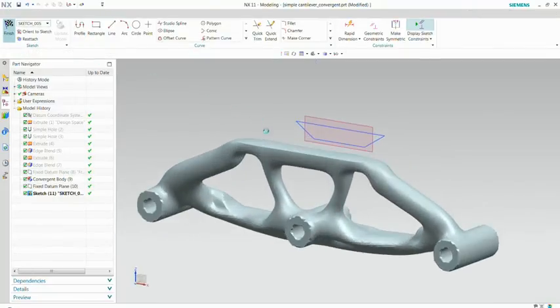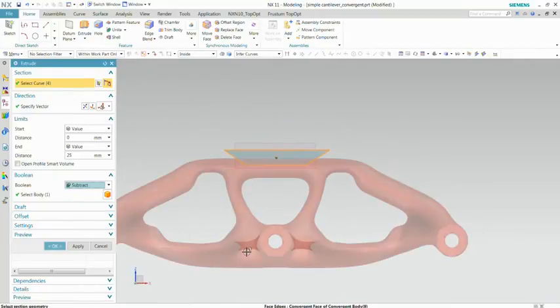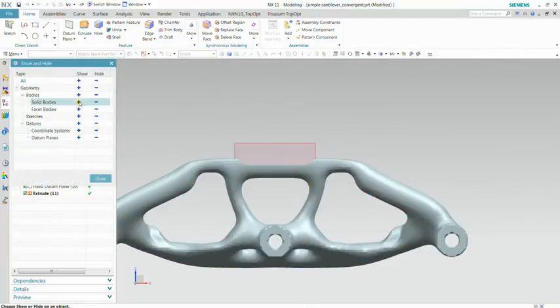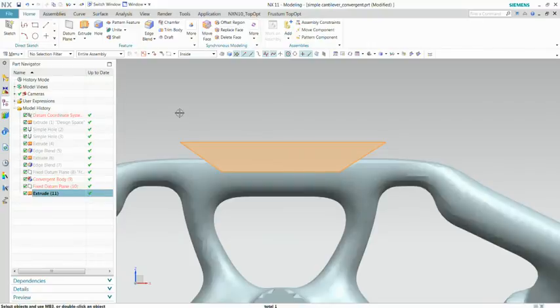So I'm defining this shape, and when we say that we can combine it with faceted models, I can subtract, for example, this shape from this part, and as you can see, let me just hide the data plane. We just created in this faceted model and cut out using a classical modeling operator and this shape.